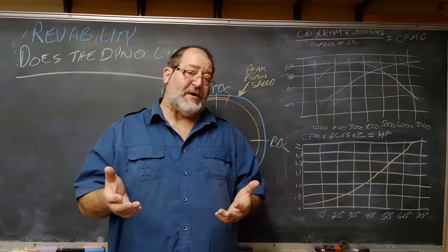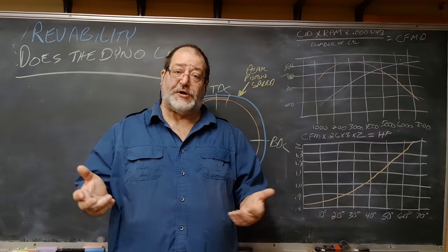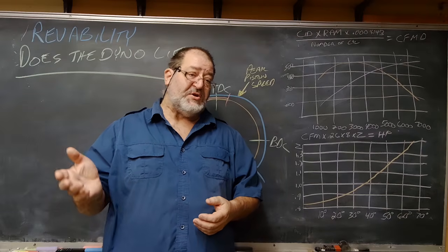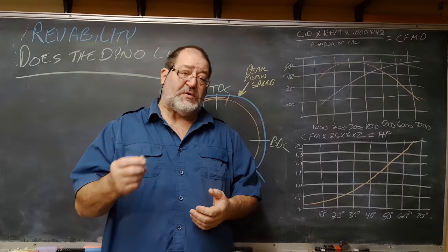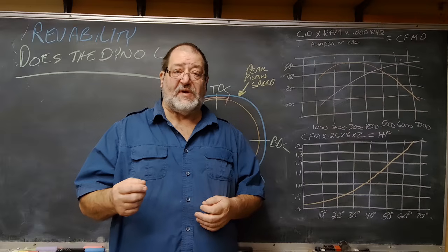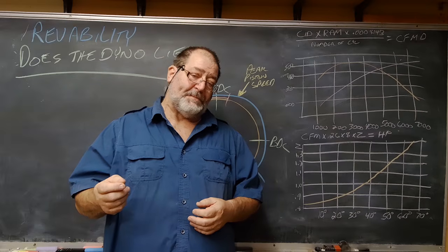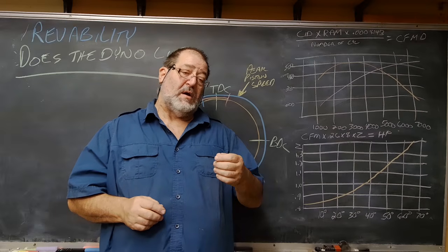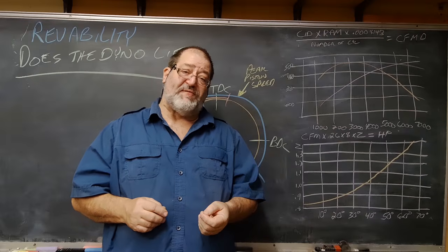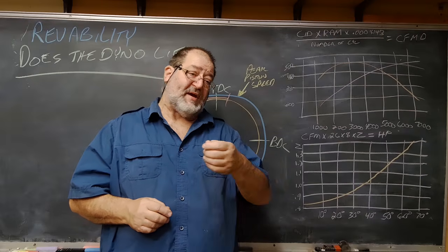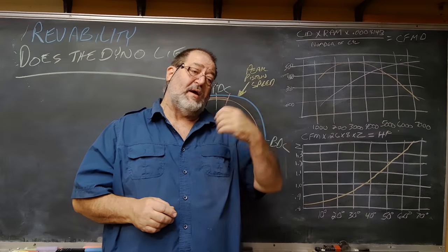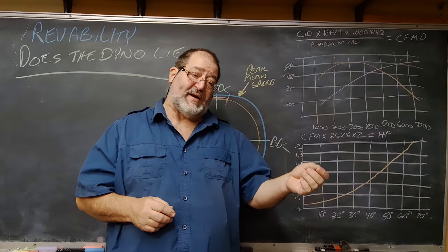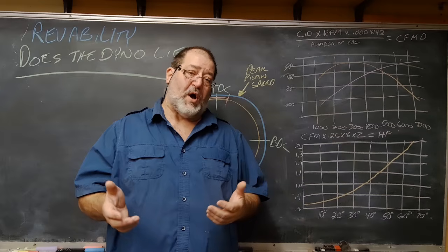And what I wound up building was a tractor. The engine, I didn't understand at the time. Peak torque on the engine happens at like 2,800 RPM. And the converter was 2,500 stall. And the gear ratio in first, between first gear 2.48 and rear gear 3.90, was almost 10-to-1.